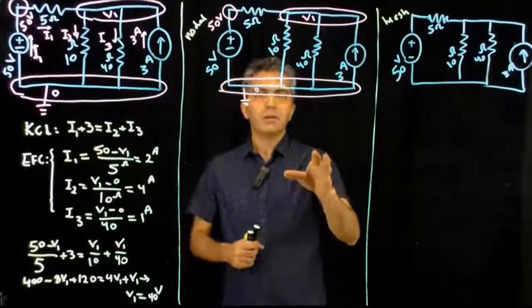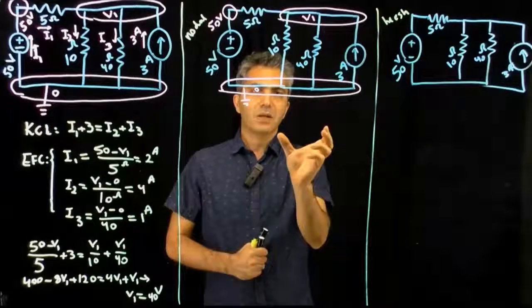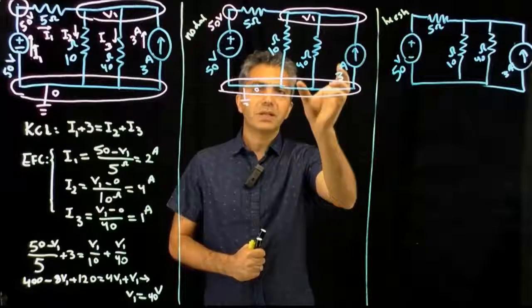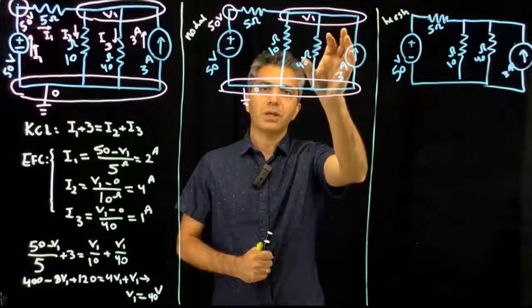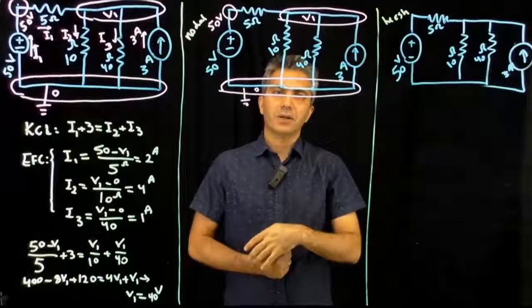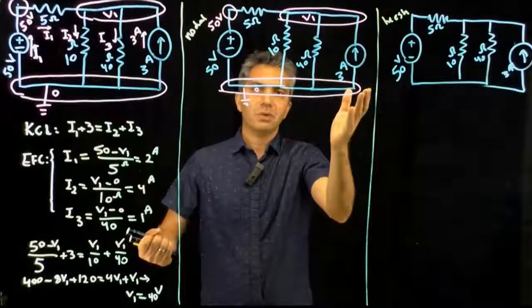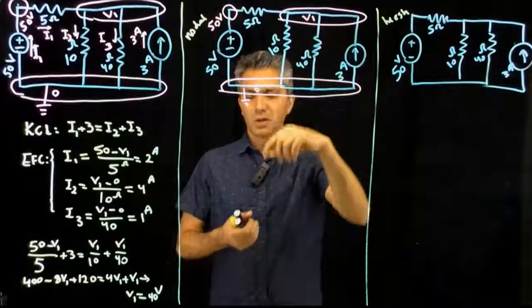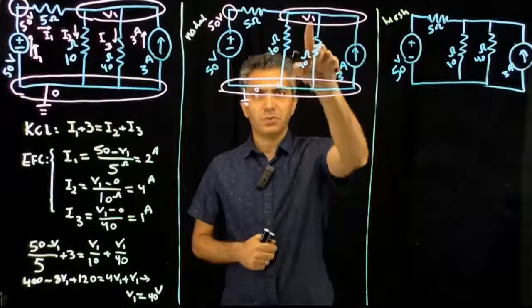Now, why are we doing that? The technique is optimized to relatively quickly give you the voltages, or electrical potentials, of nodes in the circuit. Since you already know the potential for these two nodes, you don't need to write any equation for them. You write equations for any node with an unknown potential, which in this case is V1.